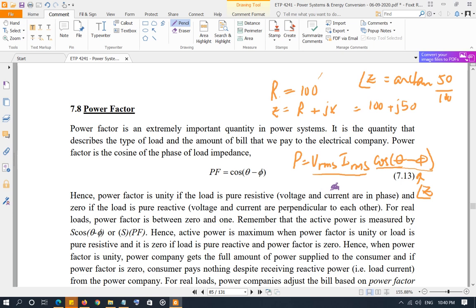Now if you do have an industry, then what they do is they do power factor correction, or they ask you to do power factor correction. So they're going to make some correction in the meter and say, if your meter is reading this, this is the actual bill that you will have to pay, because of course the meter cannot record the extra current that you're pulling to power up or excite the field, because your power factor is less than 1.